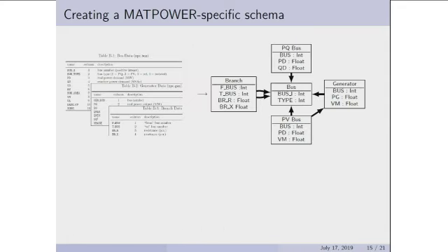Here we just looked at a particular tool that's commonly used, mostly in the academic power research literature. MATPOWER is implemented in MATLAB. If you go to the appendix, they have some nice tables that tell you how to fill in your schema. I've only shown you some of the attributes, but this is your bus table, and it tells you all the fields and roughly what they are. Similarly for generators, branches, and so on.